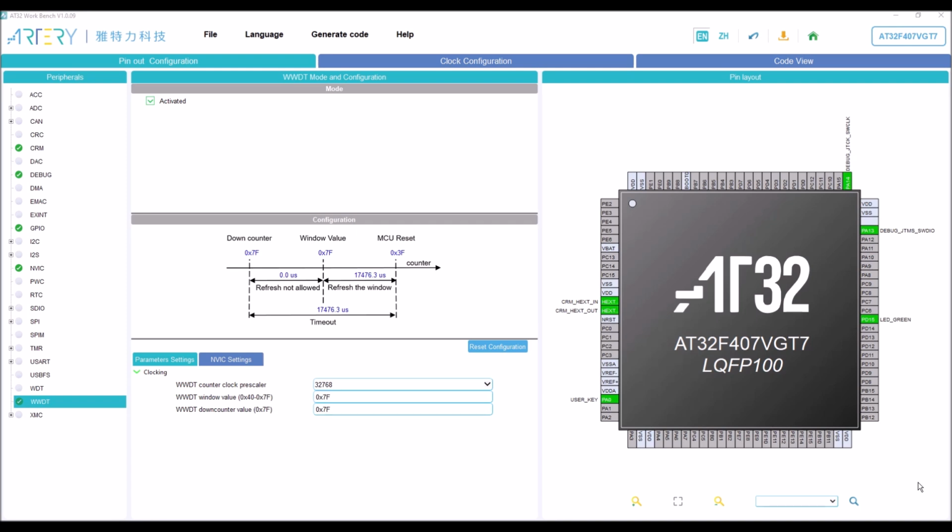One input on the microcontroller is for the push button on the board, one output is for activating an LED, along with the programming terminals, and the ones where the oscillator crystal is connected. What I've enabled this time is the Watchdog option, which can operate in window mode. In this option, if the timer is updated too early, it causes a CPU reset. In my case, I don't want the timer to function that way.